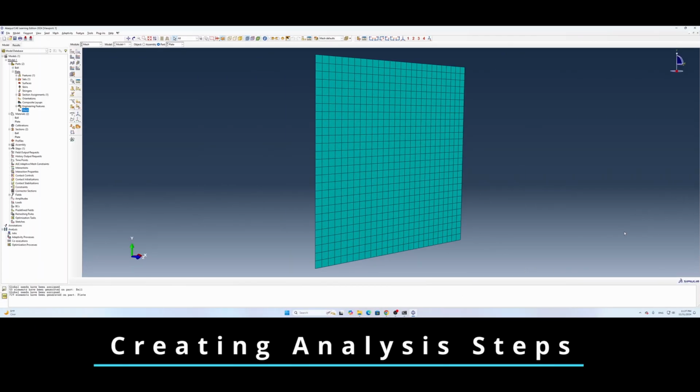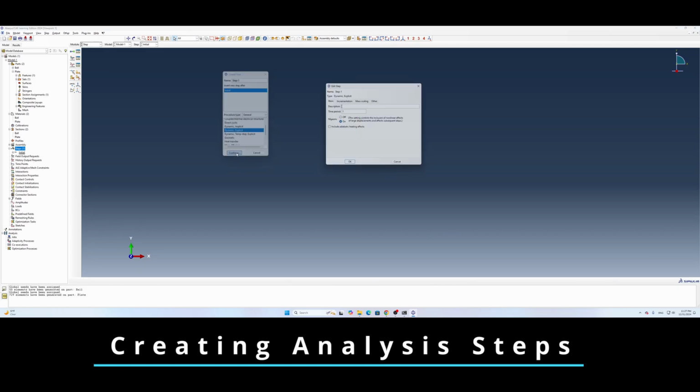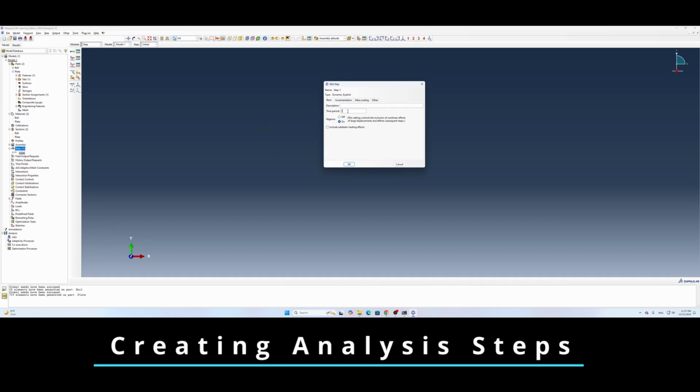Alright, so the next step is to create a step. So to do that, we go to our step, then double click, then create step 1. The step 1 is after our initial step. So the analysis is going to be a dynamic explicit, and hit OK, continue. And then for the time period, I'm going to choose 0.05 second and hit OK.